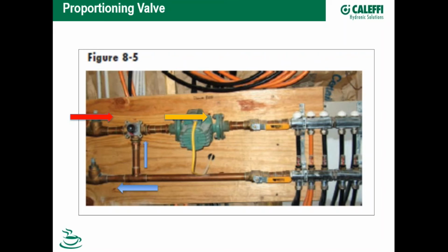So when I look at delivering multiple water temperatures, it becomes: let's drive a water temperature out of the boiler, and then let's apply, it could be a thermostatic mixing valve, it could be a motorized mixing valve, it could be a proportioning valve, or it could be injection pumping to give me that second, third, or fourth water temperature, depending on what we need.